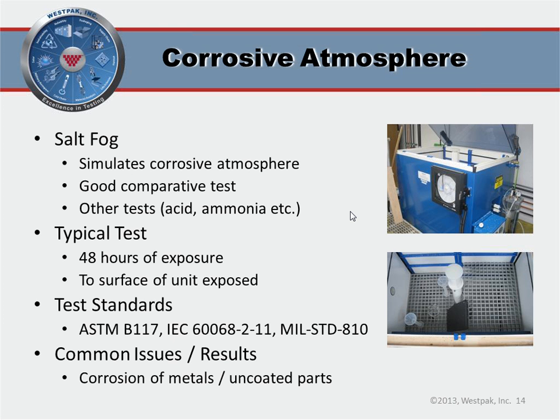One other thing to keep in mind when you do this testing is that in the test, only the surface can be exposed. The chamber is very still air and it falls down. In the operating environment, you might get some salt going into your unit or corrosive atmosphere going into your unit. So think about testing the internal components of the unit separately.